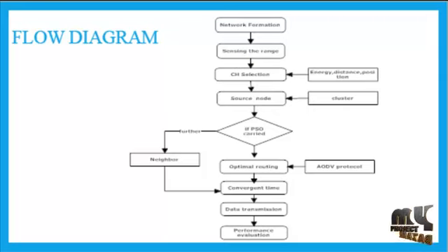We implement PSO in the WSN using the fitness function calculation, which includes three parameters: position, velocity and speed of each node, and energy based on the TX power, meaning transmit power, receiving power, idle power and sensing power. This finds the optimal routing. In our PSO, we maintain the routing table, which provides better network lifetime.